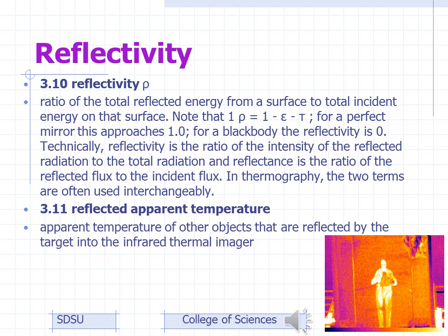Well, and there I am as promised, reflected off a piece of 316L stainless steel. You could just about paint this with black paint and get the same image, because that black paint would push it into the device and it would reflect back. I've actually seen that happen with dark brown paint in particular. So rho, Greek rho, is the reflectivity, epsilon is the emissivity, and tau the transmissivity.